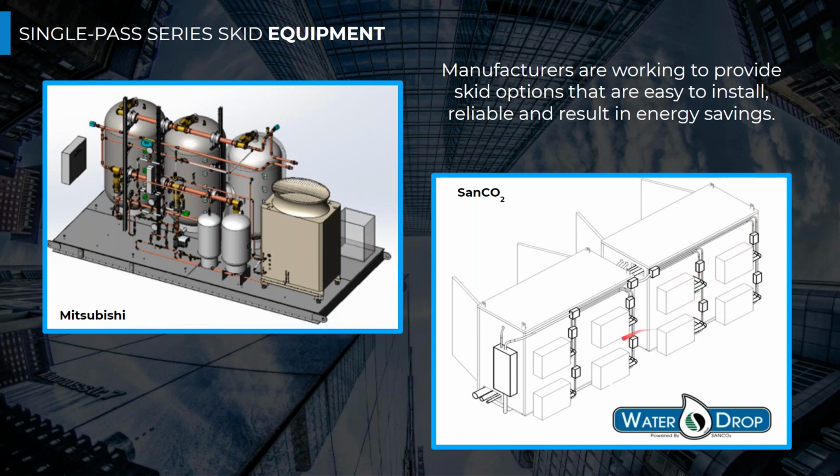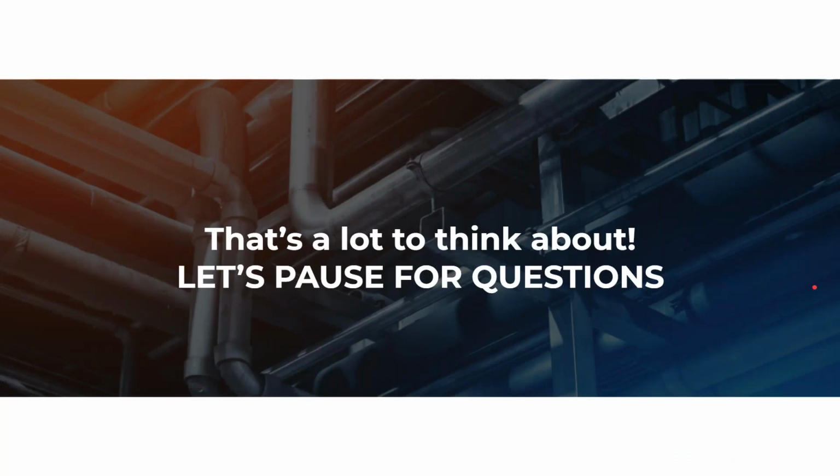And then you're adding another cabinet, which adds storage and heat pumps. And so you can couple these together to really utilize this small residential product to serve bigger buildings, but without having a bunch of field piping work needed to be done. And it's still one central plant, so it's one maintenance point rather than multiple maintenance points, which can be advantageous for maintenance contract personnel. So we demonstrated that this was a great system design, and the manufacturers are definitely jumping on board with this for their products so that we can get really highly efficient systems in these multifamily buildings or other buildings that we're working on.